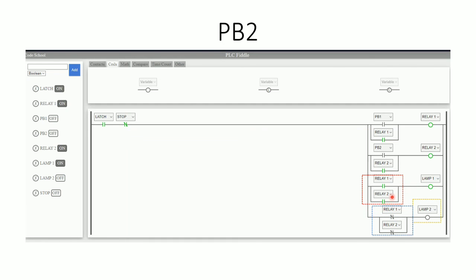And then you can see relay 2's normally open contact turns to close, so lamp 1 remains in the on state. But before this happens, as we can see, the relay coil will be energized.